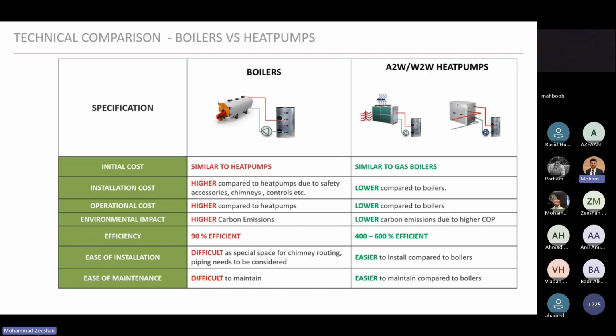Boiler systems, as you know, a lot of hotel chains across the Middle East are concerned about sustainability. So it's important that we show here a comparison between boiler systems as well as heat pumps. Initial cost for boilers and the heat pump systems are similar. Installation cost is high for boilers because you need to install safety accessories, chimneys, a lot of controls. So it becomes a challenging task for installation.